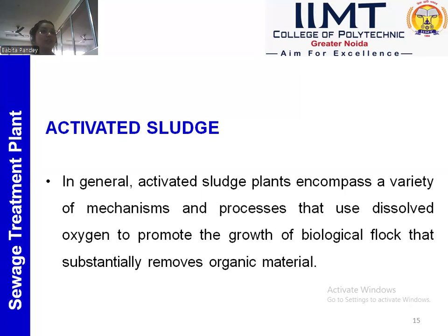Microorganisms oxidize all the organic matter, and they get heavy and dense, and they settle at the bottom of the clarifier. That is known as activated sludge. Okay, and in general, an activated sludge plant encompasses a variety of mechanisms and processes that use dissolved oxygen to promote the growth of biological flocs that substantially remove organic matter.